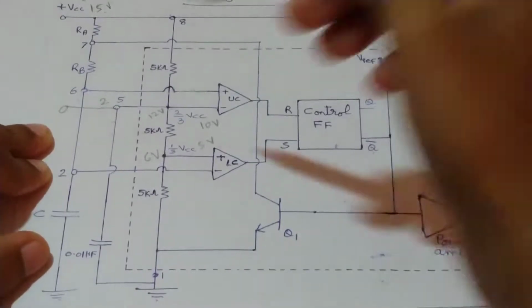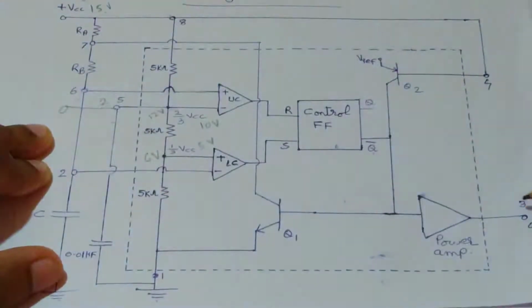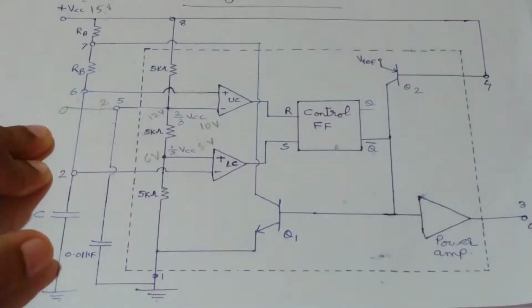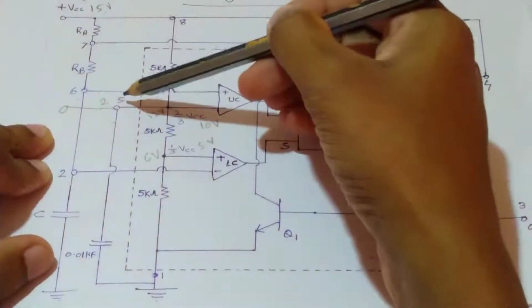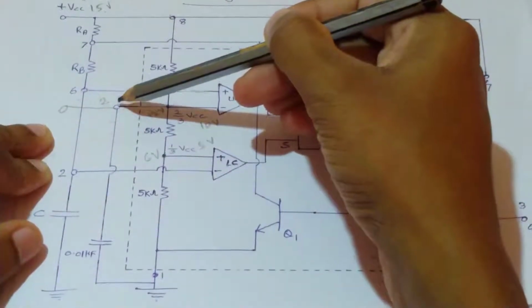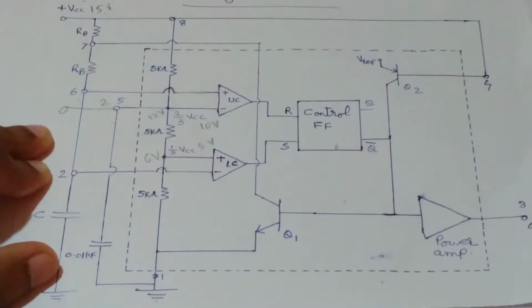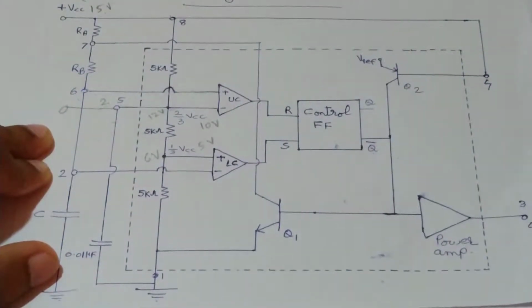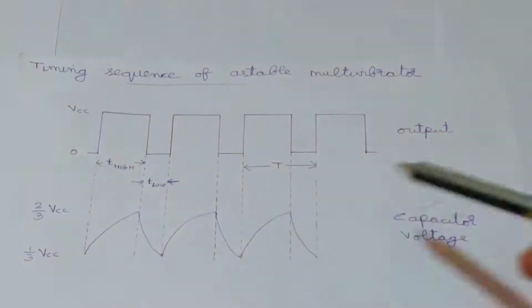Okay, so depending upon the voltage at the fifth pin, the width of the pulse changes, and hence the position of the trailing edge changes according to the instantaneous amplitude at the fifth pin, and hence we will get a pulse position modulated output signal here. Let's now try to understand that working with the help of this timing sequence.